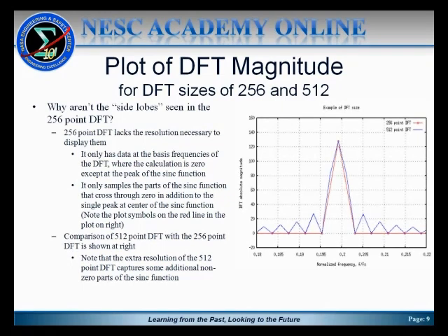And you can see that very carefully if you look again at the figure on the right, where this time I've shown just the 256 point DFT and the 512 point. I excluded the higher resolution one. What you'll see is the 512 point has one additional point that the 256 point doesn't. Each of them goes through the same points where the 256 point DFT had a value of 0 other than at the peak, and the 512 point has an additional point in between those two where it's non-zero as well.